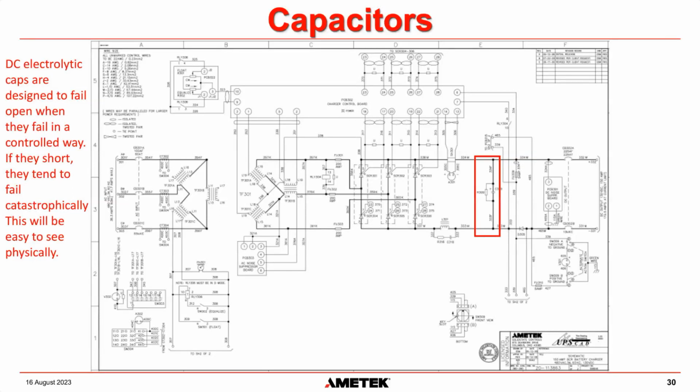Okay, so there are some circumstances where it can fail low resistance and cause issues, but it's very, very rare. So when you're checking capacitors, the first thing you need to do is physically look at them, and if anything seems damaged, then you have a problem.